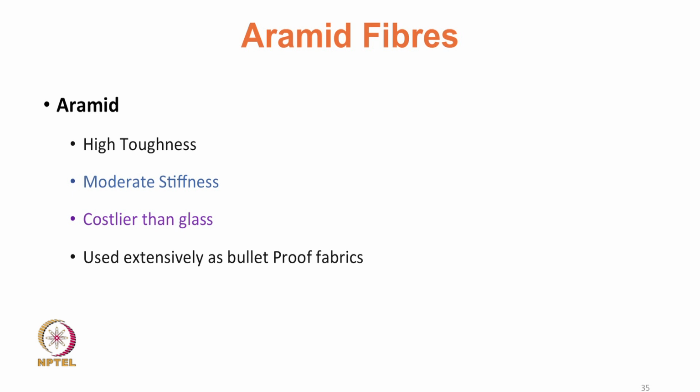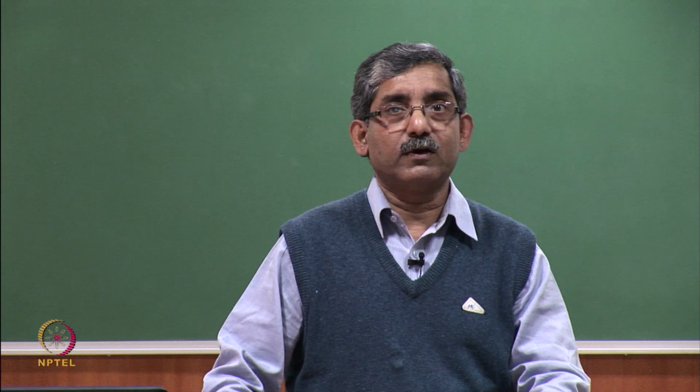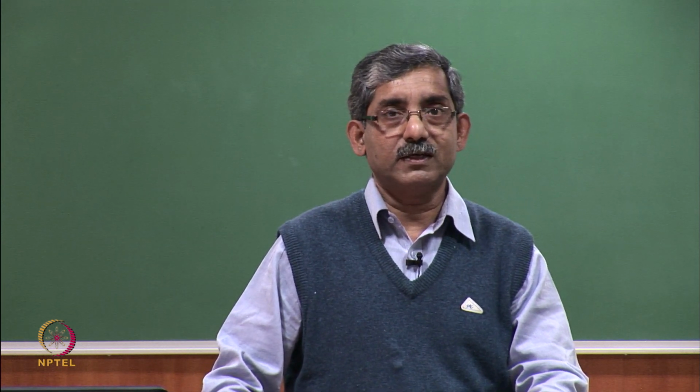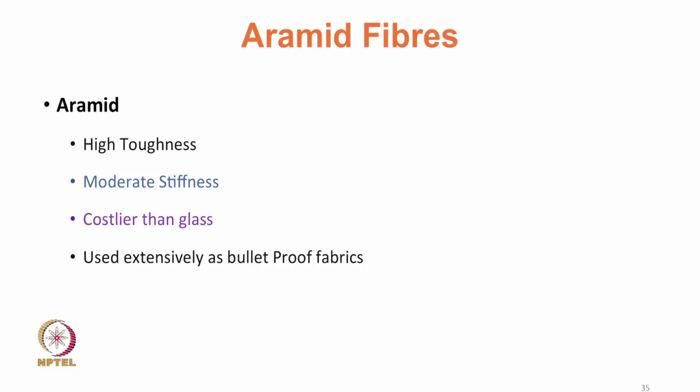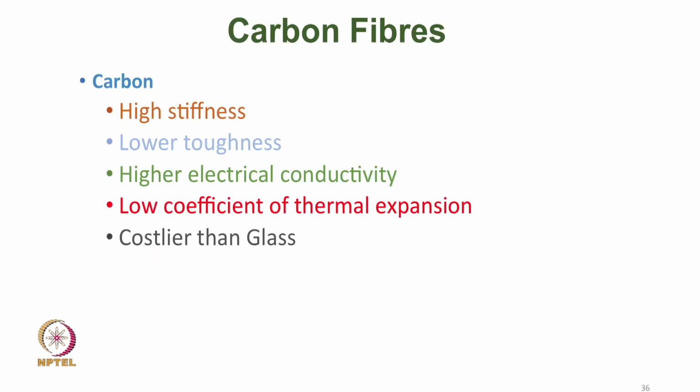So, if we want to use this fiber for very high end application, Nomex is normally used for high temperature resistant composites. Carbon fiber has the quality of good modulus at high temperature, excellent stiffness, it is an expensive fiber, it is brittle, with low electric insulation properties.